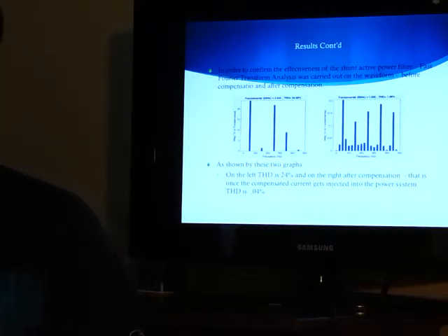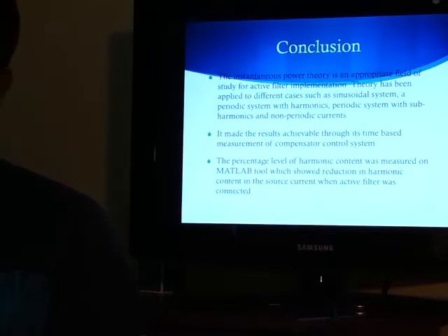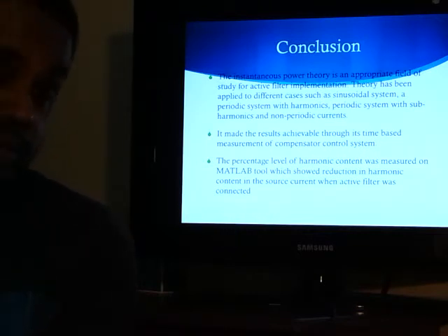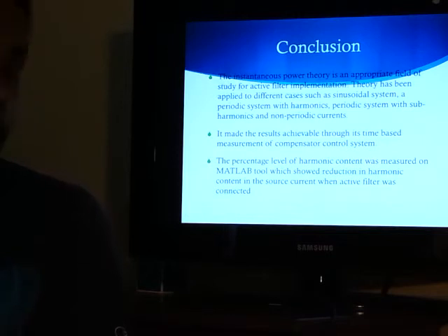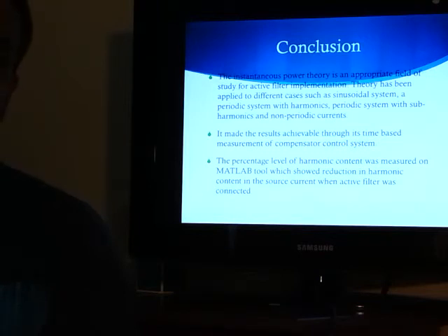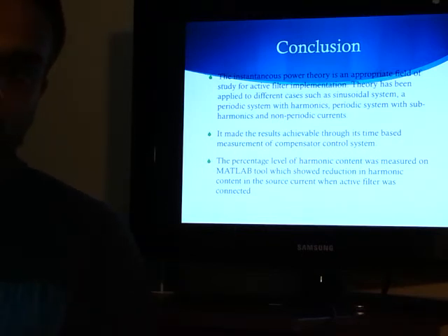In conclusion, the instantaneous power theory is an appropriate field of study for active filter implementation. It has been applied to different cases and different loads. The line impedance has been varied, and yet we are able to compensate those harmonics in the system and get the real active current from the supply. So basically, the use of the active filter has been effective, and that is proven through simulation in MATLAB.